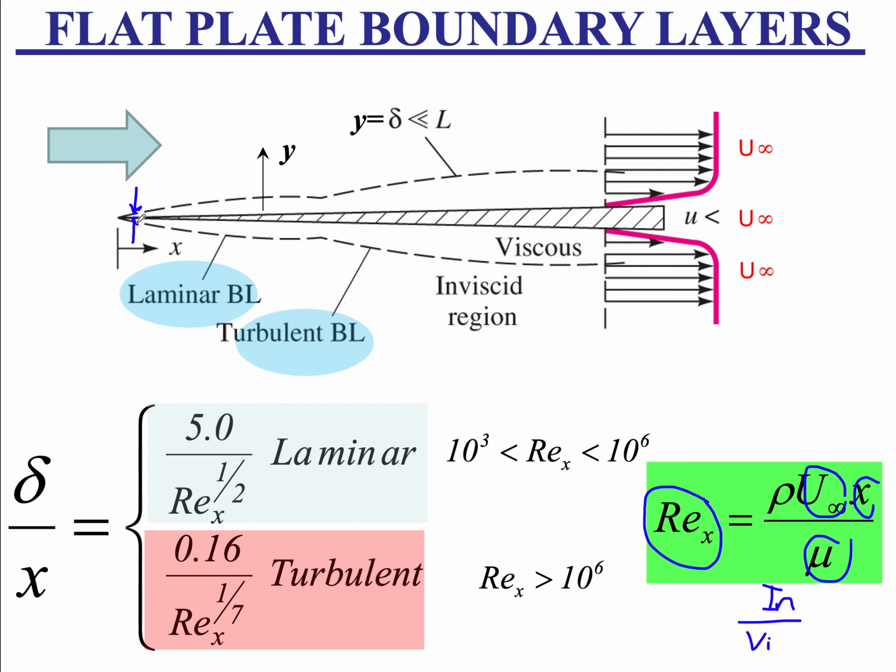If I do just scaling, I have a velocity u infinity far away from the flat plate, at the edge of the boundary layer, and at the flat plate I have a velocity of 0 due to no slip. But if my thickness delta is small, close to 0 near the leading edge, what does that tell me about my strain rate du dy and about my shear stress?